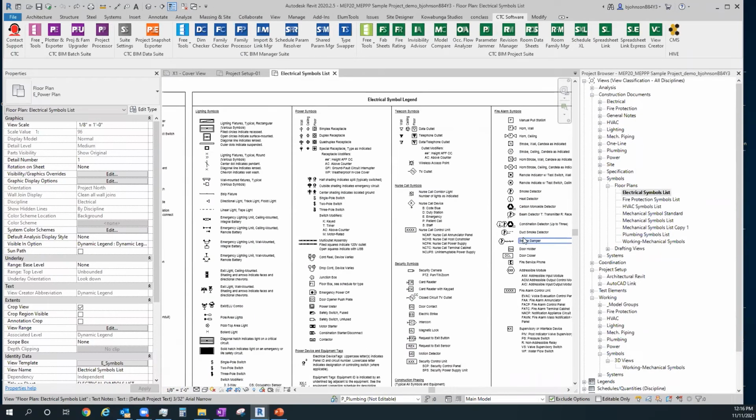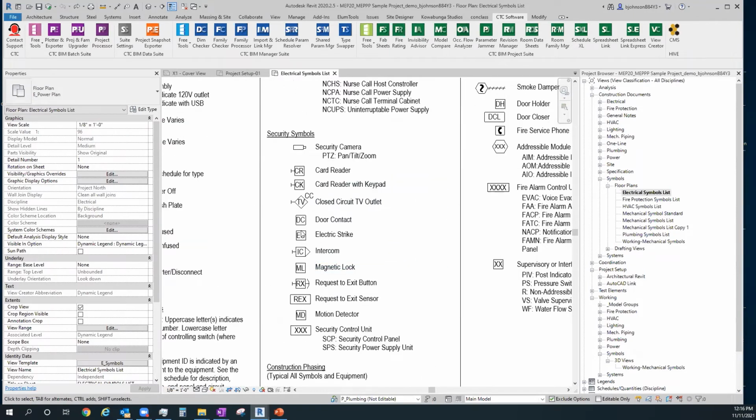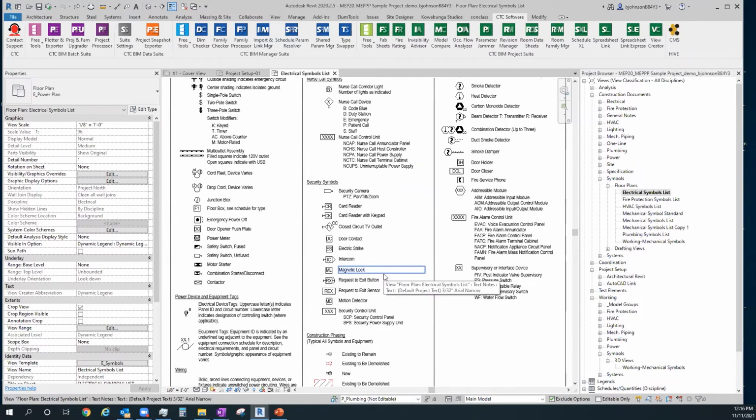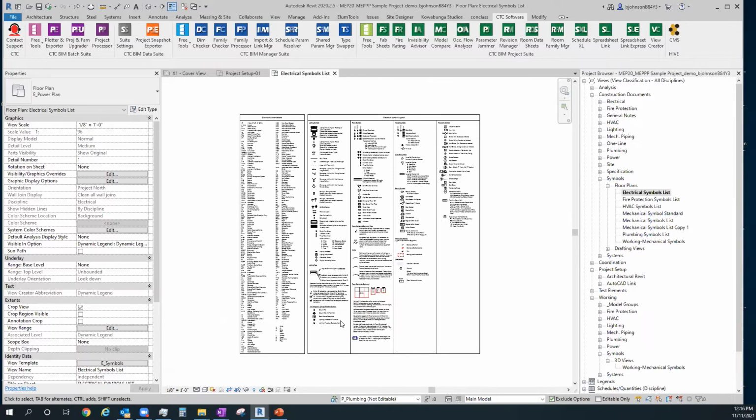So every time I'm in my model, all of my elements that I'm showing here are exactly the same. Some of these even have description tags where the description is an actual tag rather than just a piece of text. So inside of a family, I can have that description reference and actually tag these in my symbols library and have it autofill, rather than me having to type something out and maybe from project to project have that be a different thing that somebody types, or a different engineer wants it ordered differently or something like that. If it's just a tag on a description, all those are filled out easily and naturally, and they're all the same, which makes me very much a happy camper about standards, because people can't change those automatically without saying, well, delete that tag and put in text instead. So little things like that are great features inside the pack.